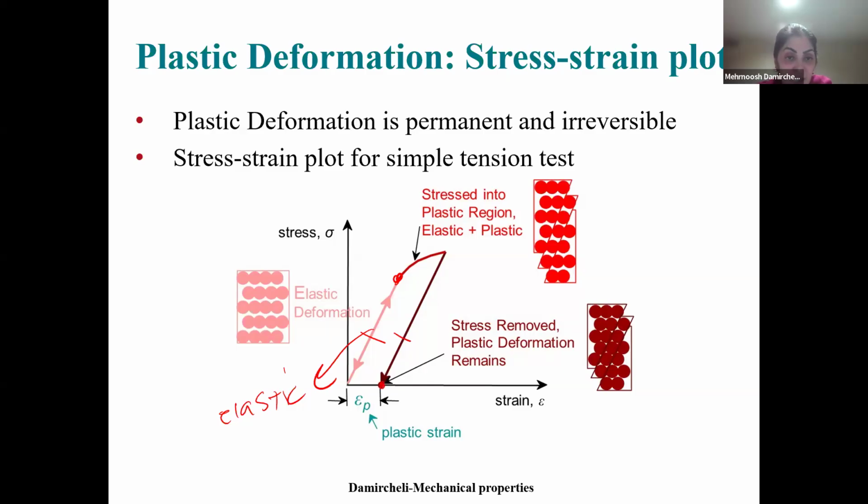This permanent epsilon is the permanent strain that is irreversible and will remain in the structure. There are some ways, such as applying force in another direction, to remove this, but today we will not talk about that. If we apply stress in another direction, the strain finally becomes 0, but we have some stress in the sample structure.